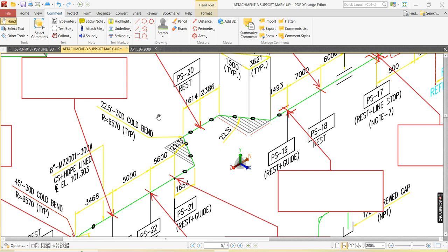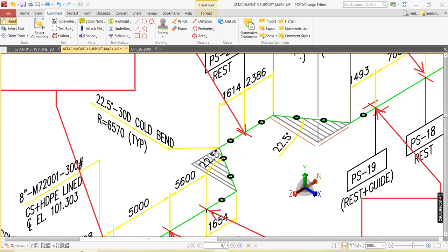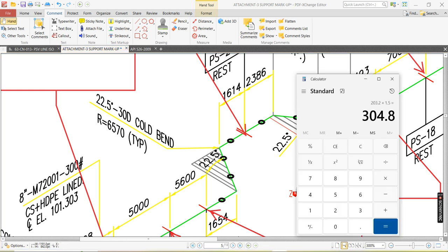So that is to provide flexibility for the piping. Okay. So 30D bend, we need to define 30D. 30D is nothing but whatever dimension, 8 inch. D is the diameter of the pipe. So 30 into diameter. Diameter means 219.1, or you can say 219. 219 into 30 is 6570. That is the radius of the bend.